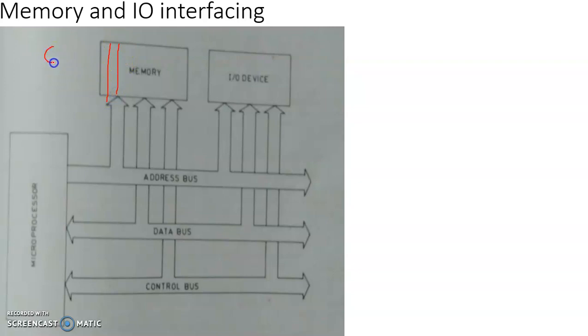Say for example, in 8085 the memory space is 64 kilobytes. This 64 kilobytes of memory will be incorporated with the processor not as a single unit of 64 kilobytes. Instead, 8 different units of 8 kilobytes of memory will be installed. This has two different advantages. The first advantage is that this gives us the facility of distinguishing certain kinds of memory from other kinds of memory, which we have already seen.